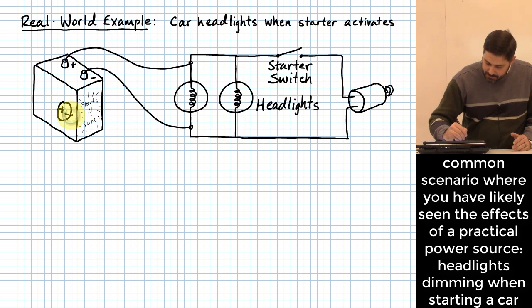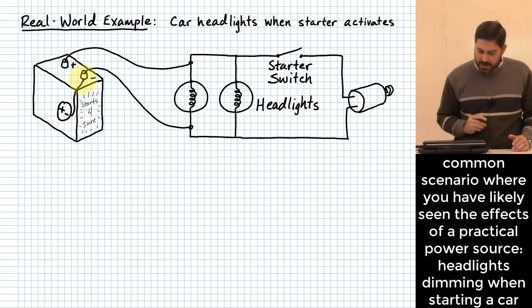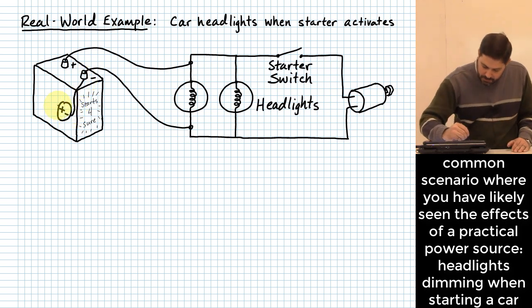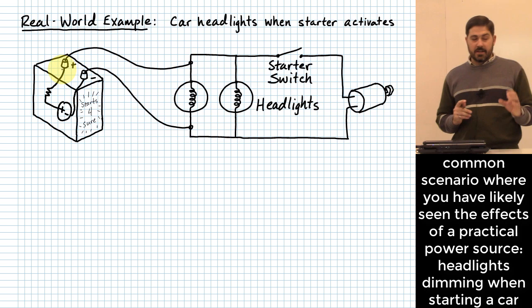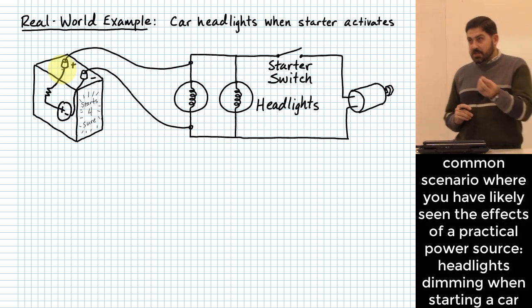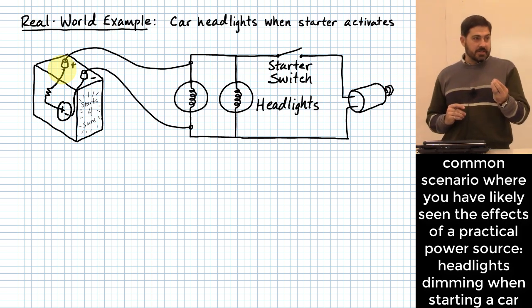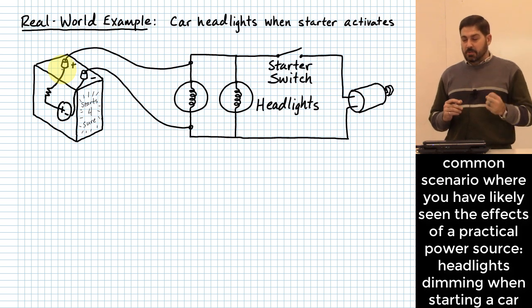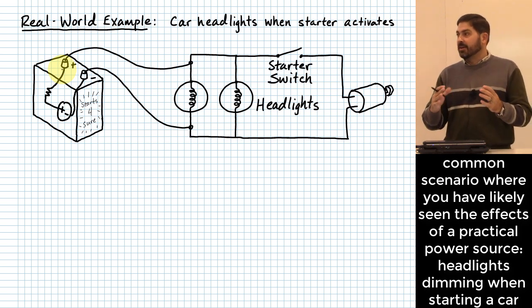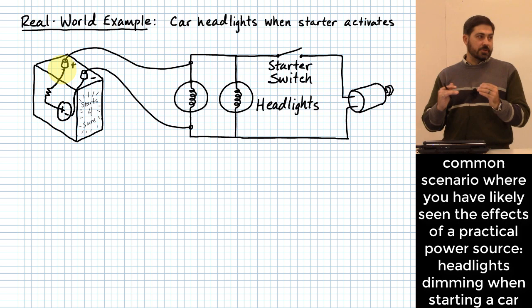And it's connected up here to this battery post. And then it goes through a little resistance value of some kind before going up into that post. Again, that is not like there's a resistor inside of there. What it is that it really has to do with the chemical process that has to go inside of that battery. That process, if you demand that it drive at a certain rate or higher, it will start to decrease how much voltage it puts out.